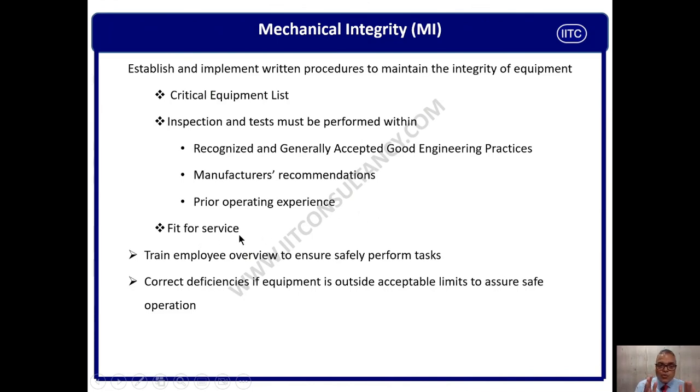Every employee who is involved in this program should be trained as per requirement, as per the TNA, as per the gap analysis. So we need to see that we correct deficiency if equipment is outside the acceptable limits. Never ever try to work on damaged equipment, on faulty equipment, because this is going to kill you. So guys, in a nutshell, we have to have an established and approved procedure for mechanical integrity.